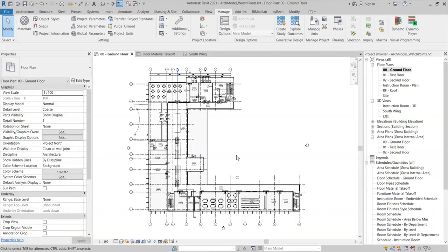In practice, we would very rarely produce initial schedules for areas of key building elements, such as walls, floors, ceilings, and materials, for example, because we cannot always guarantee the accuracy of the models to provide reliable data, especially on large projects with tight deadlines and multiple users in the Revit models.